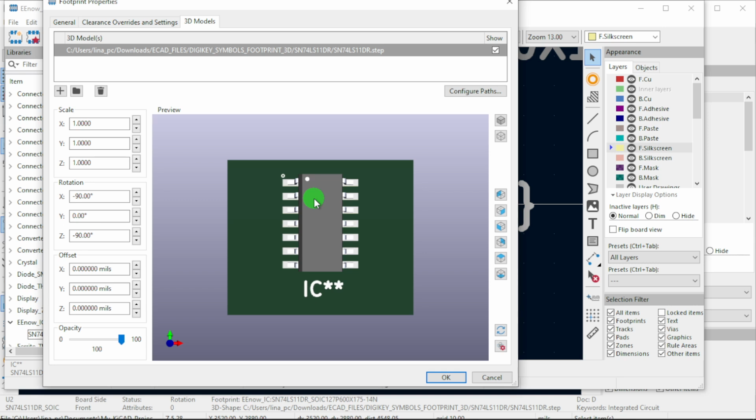And then here, copper layer silk screen 30, 39. Okay, so I'm going to leave that alone. Text thickness, I'll say 7, 7, 7 mils. And width, height, that looks okay, 39.